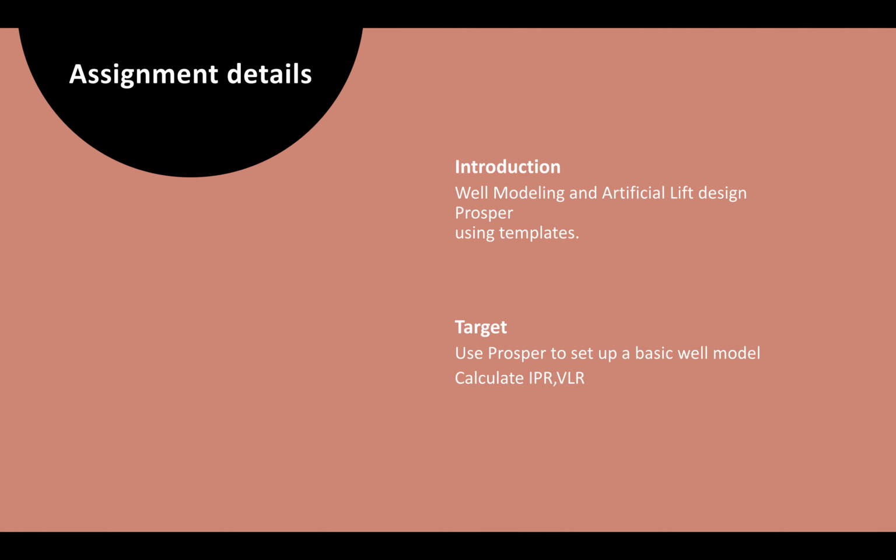This tool is the industry standard for well modeling worldwide, and in this assignment, I will use Prosper to set up the basic models, which require first characterization, PVT, IPR, and skin modeling, VLP construction and matching, and finally artificial lift design or optimization.